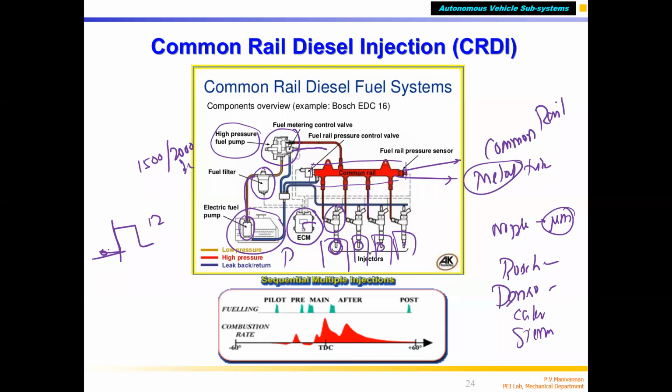In a diesel engine, pure air is drawn into the engine during the suction stroke. No fuel is added, the inlet valve closes, and the exhaust valve is already closed. Compression happens, 15 to 18 times. When the piston goes closer to TDC, a few degrees before it, the fuel is injected. That is called start-of-injection in a diesel engine, correct? The fuel will be injected 10, 20, 30 or 40 degrees before TDC, depending upon engine speed.